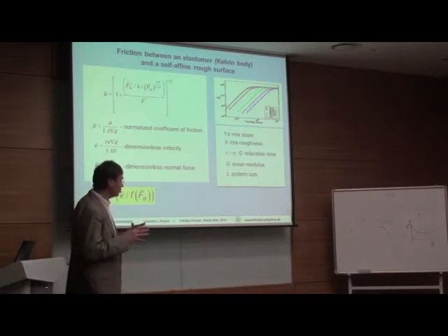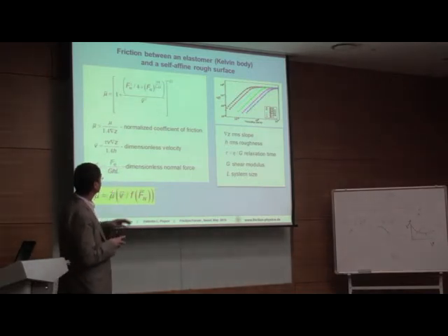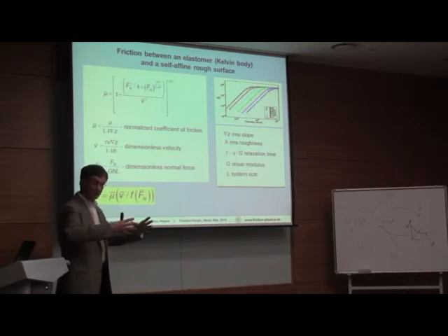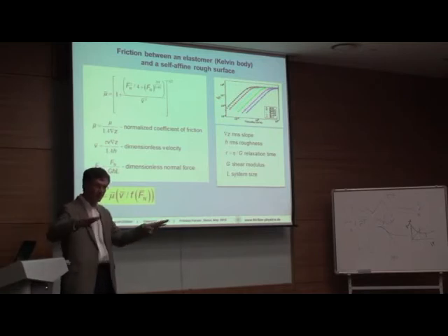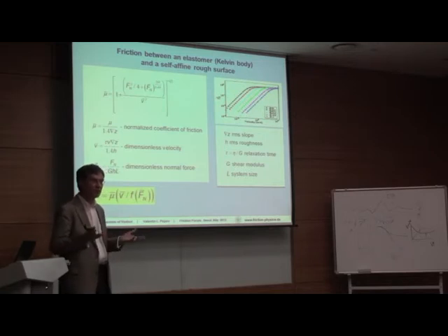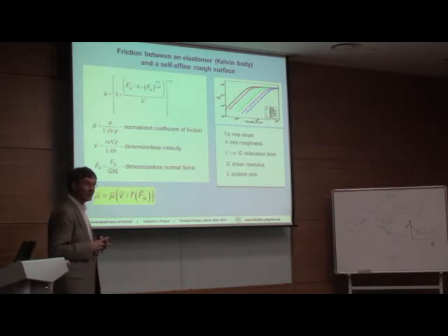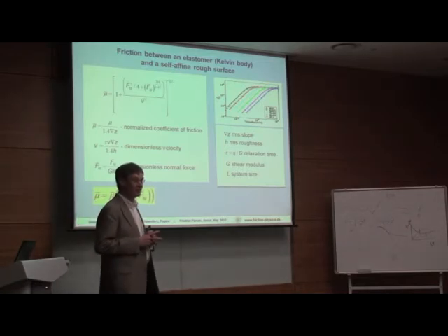Yeah, maybe to avoid misunderstandings. This is a result for a plane, not for a cone. This is for a flat surface, a pure flat surface. Yeah, so nominally flat, but in reality containing some long wave components, but not a cone. No. But that again goes down to Peter's question: why have you got G there and not E? It is the same. It's a function of the Poisson's ratio. There's a difference between the two. Yes, of course.